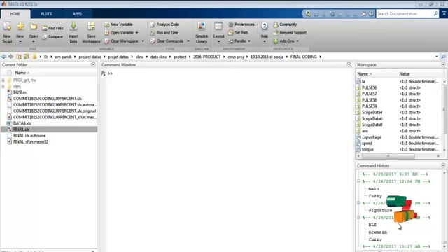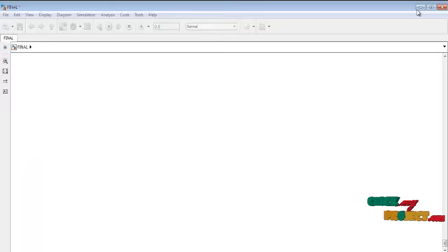Next we see about the running process of our product. This proposed implementation is done in the MATLAB simulating environment. First open the MATLAB main window. After that we create a new model file. After creating the new model file, we arrange the elements as per the circuit diagram and the given flow diagram from the Simulink library browser. In the Simulink library browser we mainly use two kinds of toolboxes. One is the SimPowerSystems toolbox, another one is the commonly used toolbox. From those toolboxes we get the elements and arrange them as per the given flow diagram. After that we click the run icon, then the simulation will start to run.